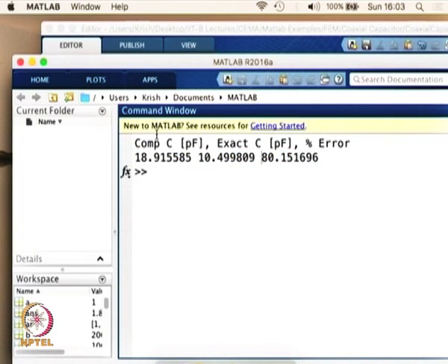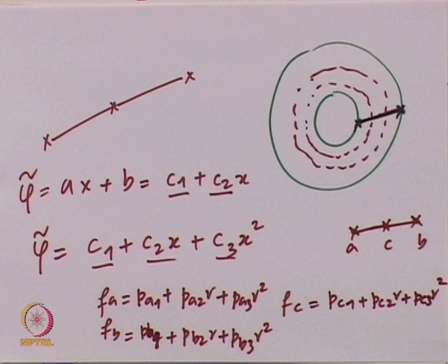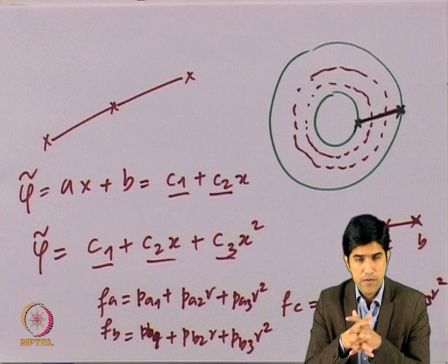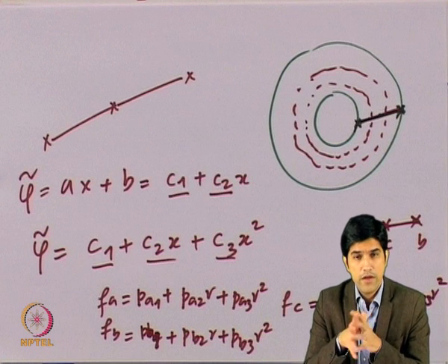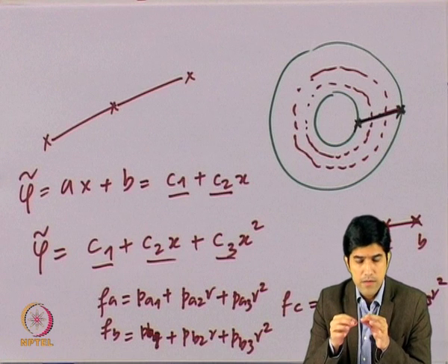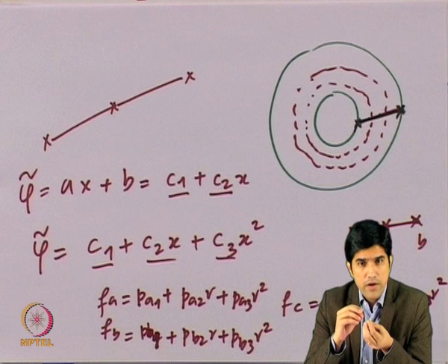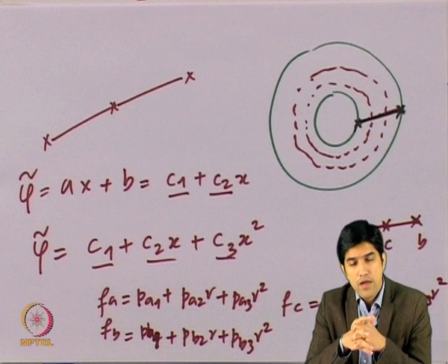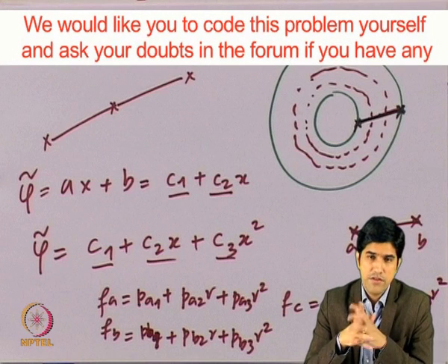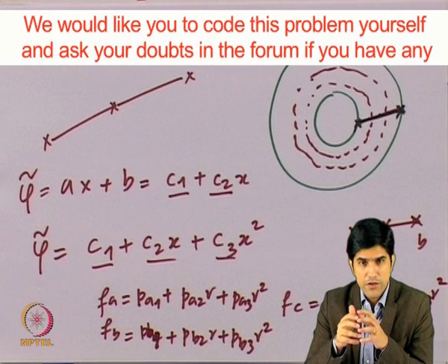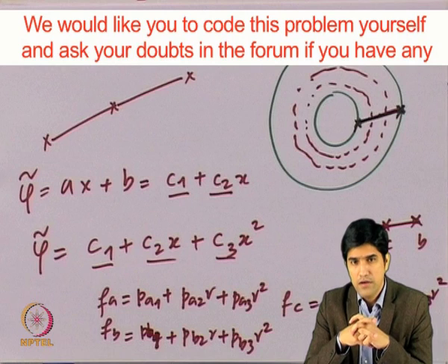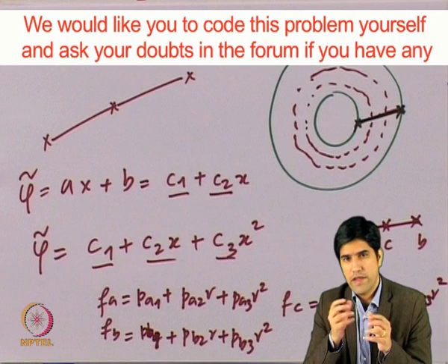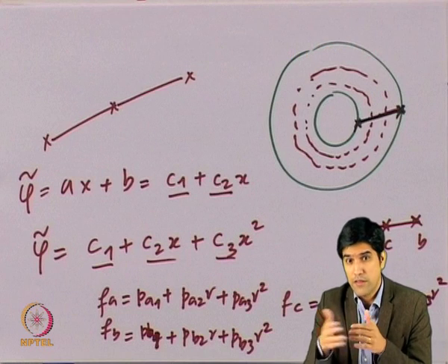So what is important here is what we are doing in terms of finite element is the number of points that we need. Second thing is the quadratic or the linear basis function, whatever basis function we are going to use is going to impact the result. And this being said, these are the most important parameters that you can tweak in modeling the finite element problem. Please practice it for yourself and change various parameters. I encourage you to try it out for yourself and learn how we have modeled it, what we can learn, and how we can extend this idea to other problems.